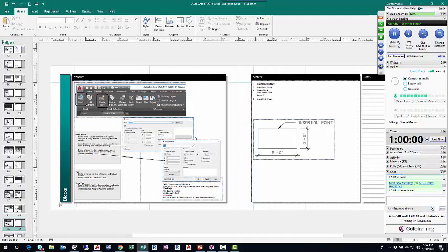And whenever you insert one drawing into another drawing, the drawing being inserted is considered a block, or technically a block reference, but very few people use the term block reference. It's usually just block. So this will happen in one of two places. I'll show you both places it happens. One of the places is on the Insert tab of the ribbon on the block panel using the Insert button. When we click Insert on the block panel on the Insert tab, the Insert dialog box will appear. Let me kind of show you this in context.